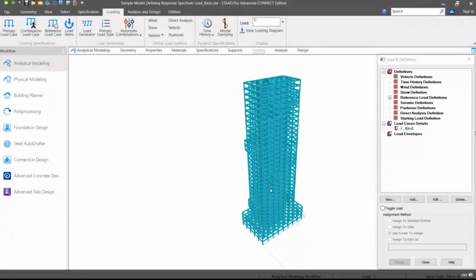So, these three response spectra load cases are created for X direction, load 1 and 2 considering accidental eccentricity value with positive and negative factor, and load 3 without considering the accidental torsion. I need to repeat the same process for Z direction. In Z direction, three separate load cases are created. Load 4 and 5 with accidental eccentricity and 6 without any torsion value. Rest of the inputs are same except direction factor which is now specified for Z direction with value 0.28.